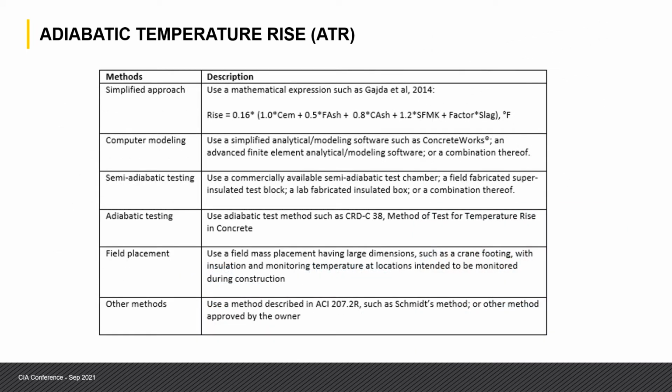And talking about adiabatic temperature rise, you need to think about what tools are available for you to assess a mix. This is what I'm showing here: different concepts that we have discussed in different committees in the North American market. The first one is a simplified approach. The simplified approach is simply qualifying the materials you're going to use. There's going to be a factor associated to that material, and then you do the calculation with a simple mathematical equation. Computer modeling is also typically used to assist in those calculations. So you may use finite element analysis to generate a model that allows you to generate heat, trap the heat, and then quantify that heat so you have an adiabatic temperature rise value.